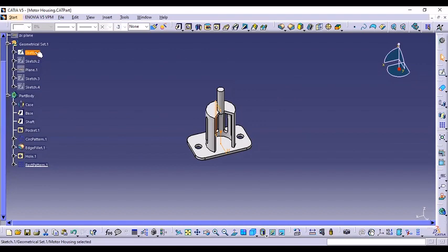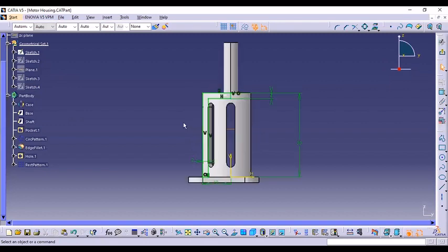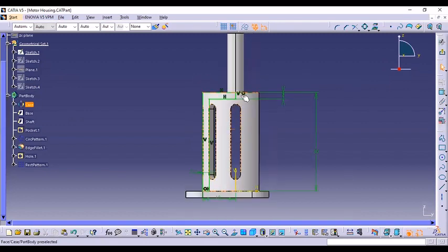So first of all, we started with the housing compartment, and the way we did the housing compartment is because we want an empty hollow inside. So the thickness of the C-section is 2 mm, and the height of the housing is 30 mm.